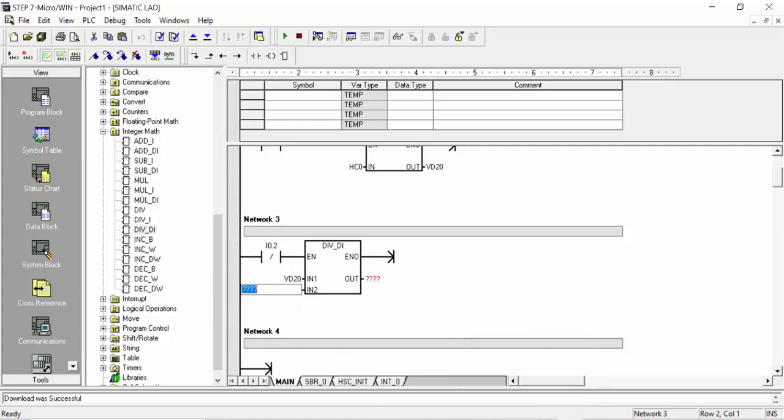4 bits, yani. You can also put a data register here. If you would like to set the set point and make changes from the HMI, you can put any data register. For example, I will choose VD25. After, I will put the value at VD25 and take it to any data register. VD, for example 30, I will choose and click enter.